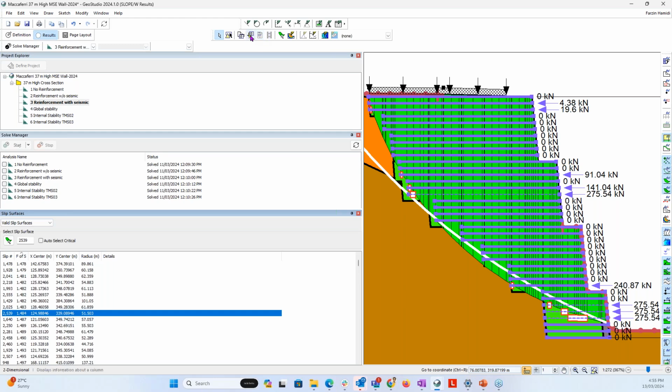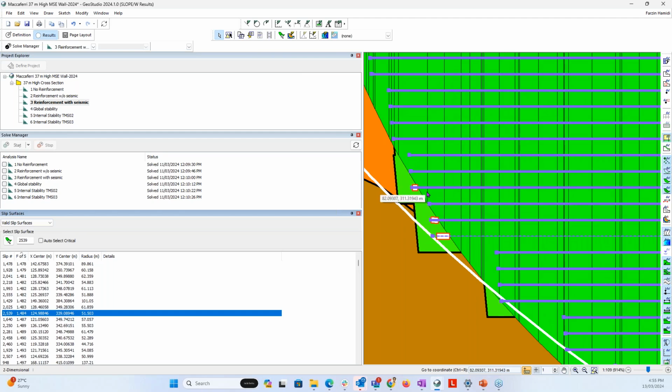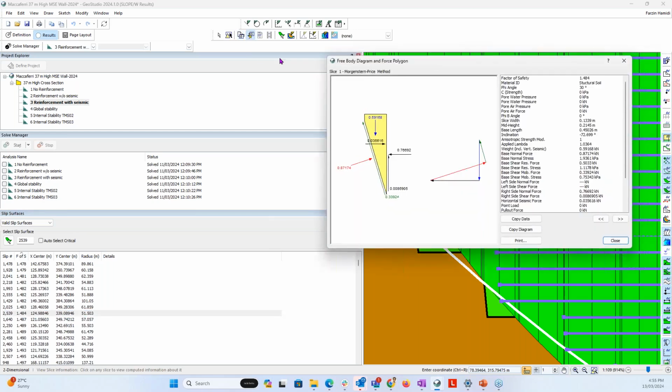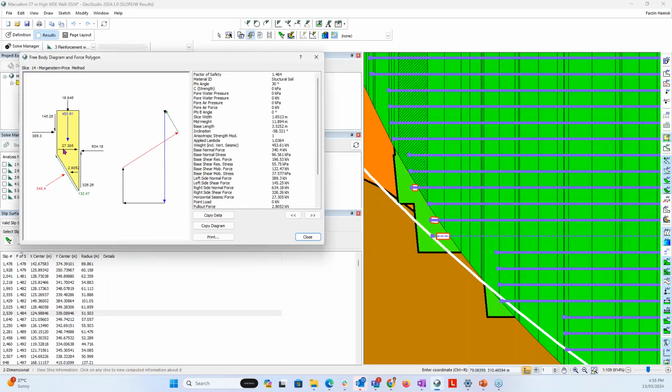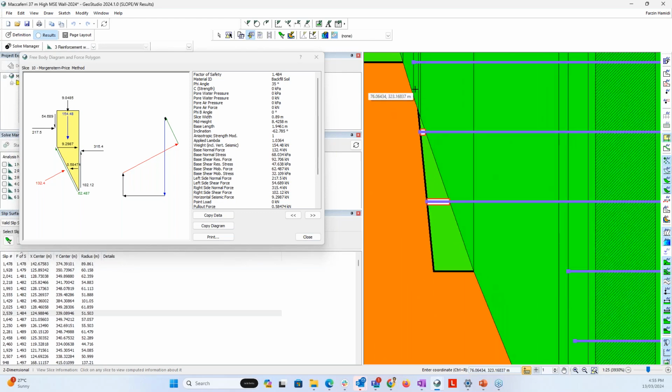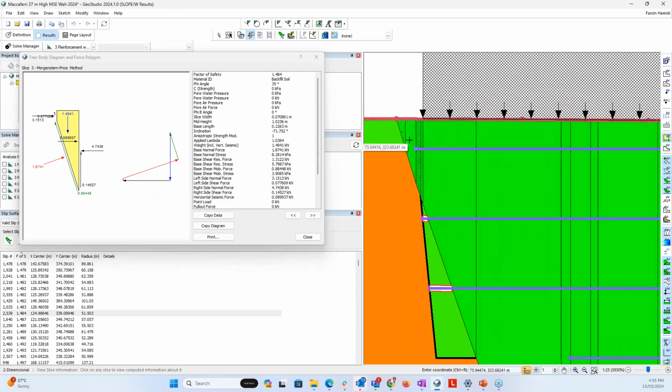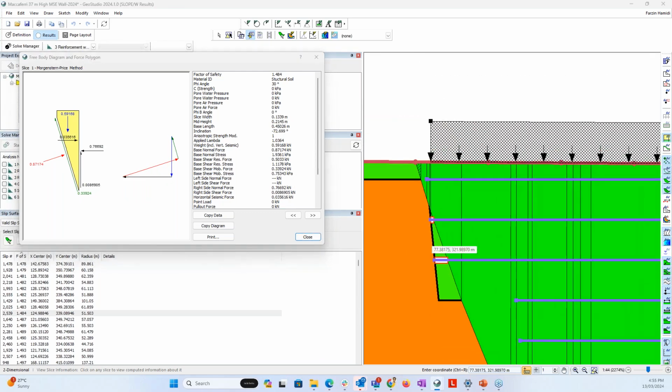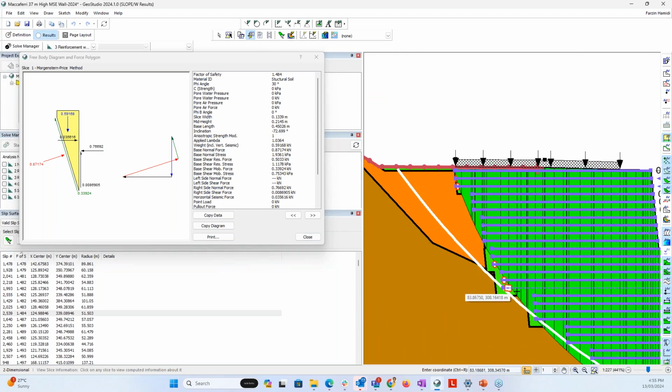Also, you can have an understanding specifically of where that load is applied. You can do that by just clicking on the slice information, and you can switch to that specific slice and you'll see this load is applied, but that is for specific reinforcements. Behind that, only one GeoGrid is applied here, and above that you see nothing is going to be calculated. So that's the only thing you need to consider in your GeoGrid and the reinforcement force option in this result view.